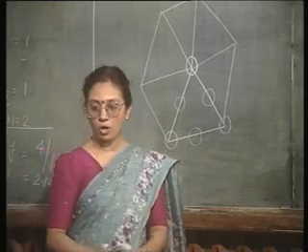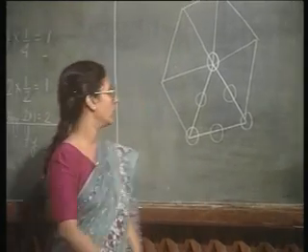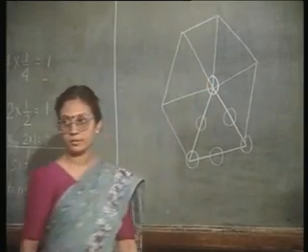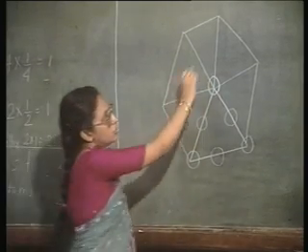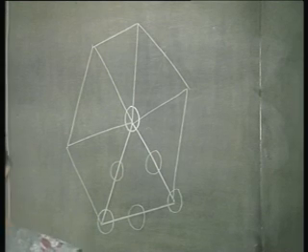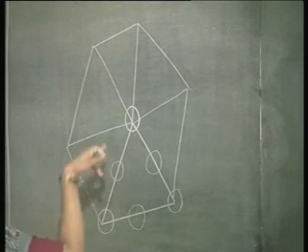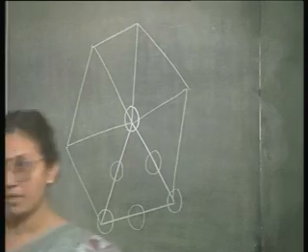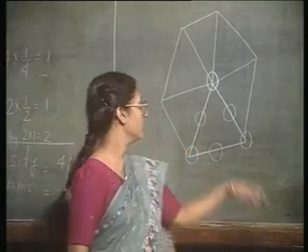These are all the possible 111 planes passing through this point. That is, I have 1, 2, 3, 4, 5, 6 planes. It is a hexagon, it has to be, right, because this is actually an equilateral triangle, each triangle having 60 degrees.